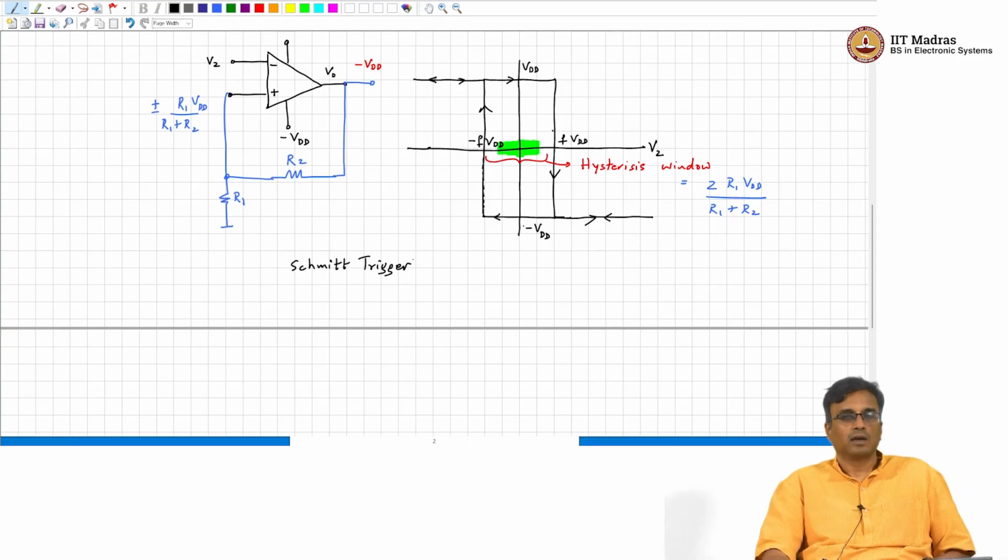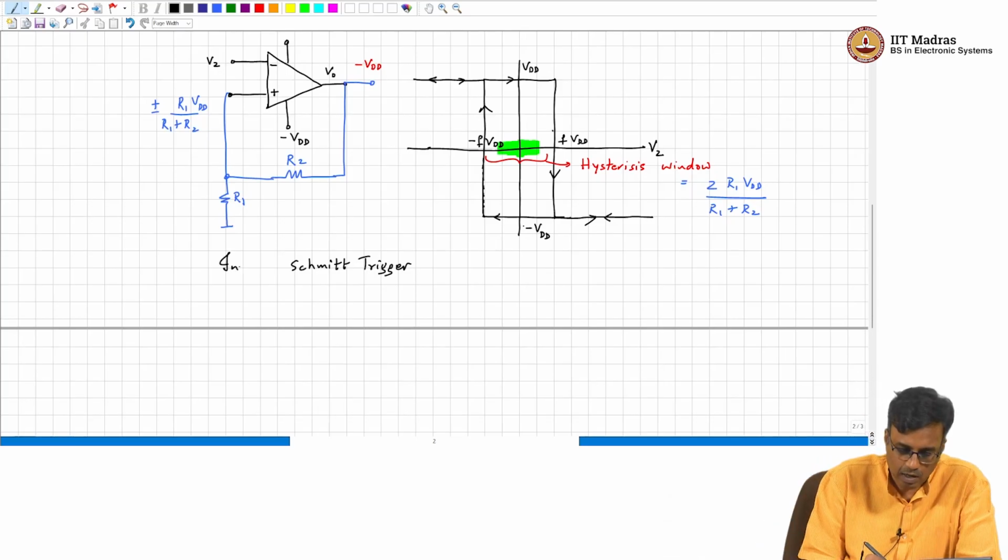and as you can see, if the input is very low, the output is high. If the input is high, the output is low. So, what kind of characteristic? It's inverting. So, this is an inverting Schmitt trigger.